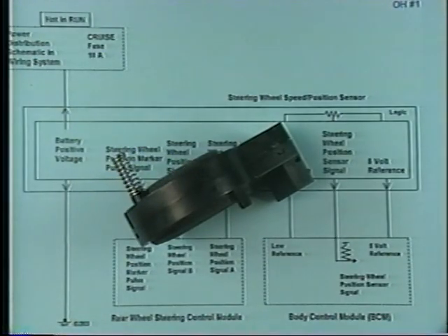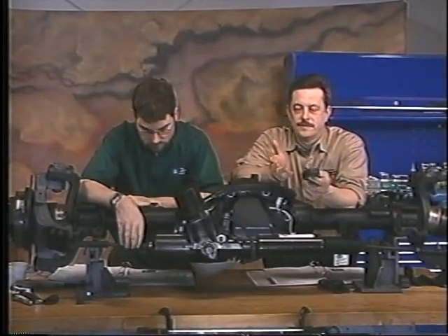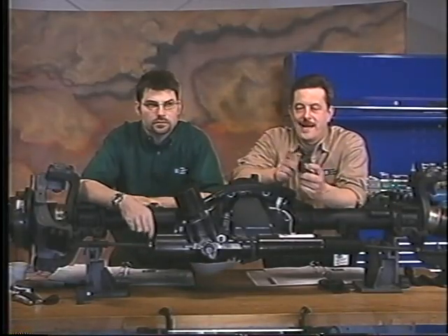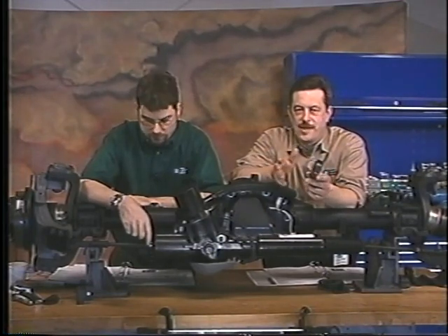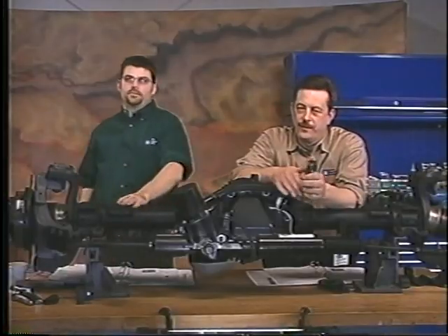All right, and also, we talk about that steering wheel position center. Obviously, it's time where you're going to take a column apart to somehow repair that column. You're not going to have a shipping pin, okay? Before you disassemble, make sure you got the column in straight ahead position. Go ahead, do your disassembly, make a repair, start putting things back together.